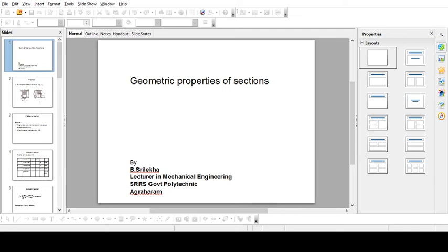Now for the y term, the base lies on the x-axis only, so no distance is there. So here we can write simply 4r by 3 pi, so 4 into 20 by 3 pi is the y term. Okay? So like this we are going to find the centroids.